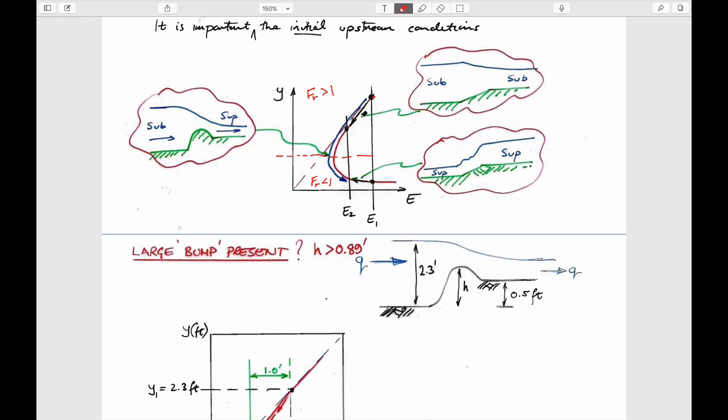If it's subcritical, then as you change the elevation of the bed by this amount, for want of a better number, W, since we used it before, you can change the depth of flow, which goes from deep to shallow as you move down here. If you start off shallow and you have the same rise, you go up the same amount here, this is also W.